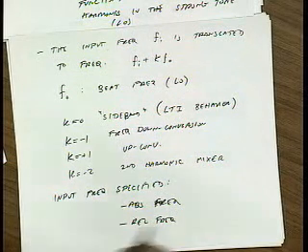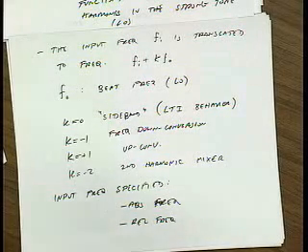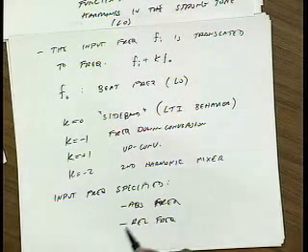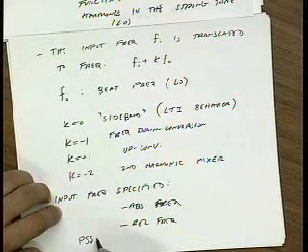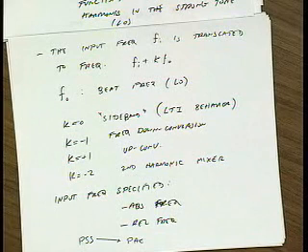Pretty clear? Yes. So PAC is a subset of PSS? Yeah. You have to first run PSS. When you run AC analysis, you first have to run DC analysis, right? You need to find the DC operating point. So first you run PSS, and then you run PAC. You can't just run PAC without running PSS. It's a good point.